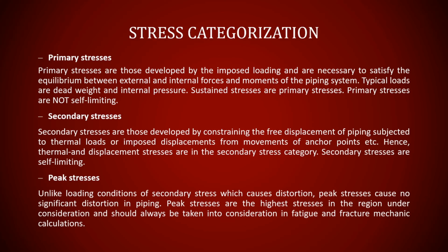Primary stresses are those developed by the imposed load and are necessary to satisfy the equilibrium between the external and internal forces and moments of the piping system. Typical loads are dead weight and internal pressure; sustained stresses are primary stresses. Primary stresses are not self-limited.